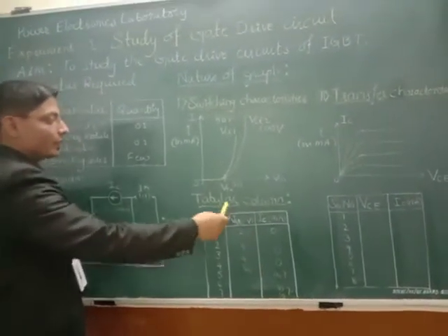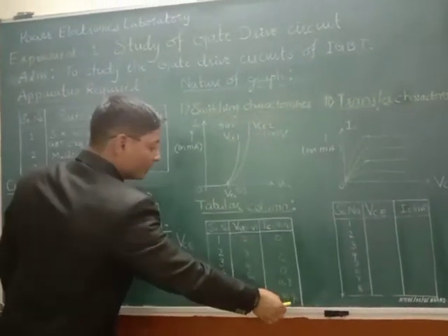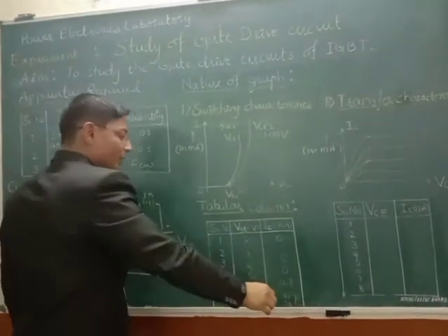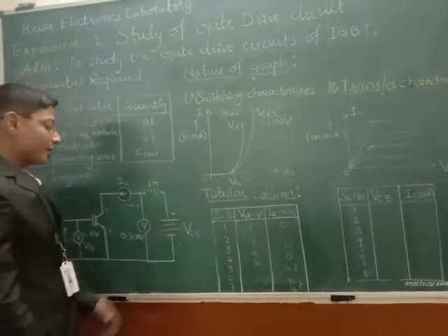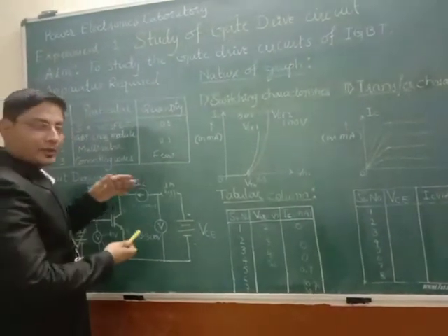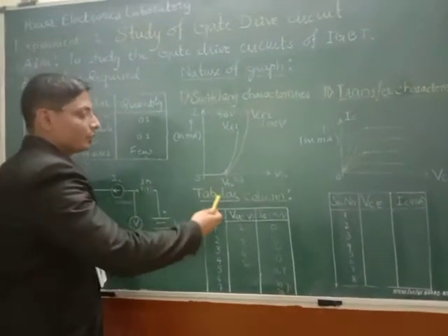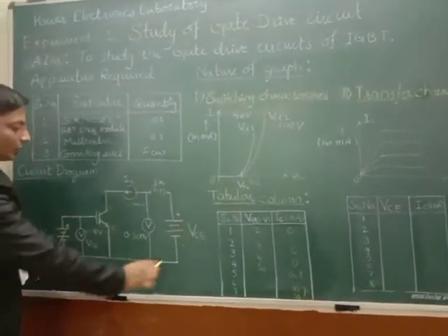So when we have 100 volt VCE, the current is going to increase to a particular value, and then again it is going to remain constant, as the applied potential difference is sufficient only to make that 75 milliampere of current flow through the circuit, not more than that.